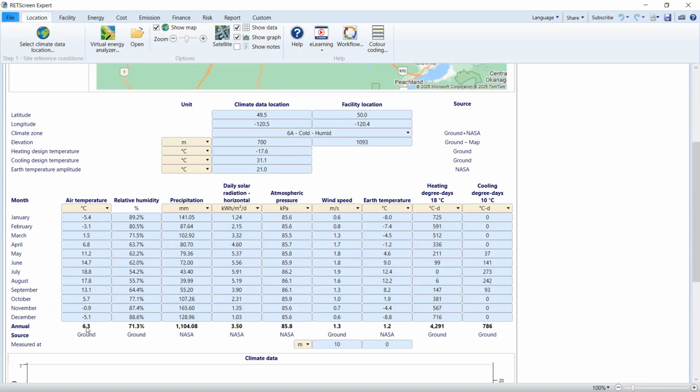And this site is a little bit colder than the standard test conditions of 15 degrees Celsius, which are used with a turbine to estimate the power output of a turbine. So the air is going to be more dense than in that test, and that'll tend to increase its output. This atmospheric pressure is lower than the atmospheric pressure at sea level, which is the assumption used when you're evaluating standard test conditions for a turbine. Why? Because we are at 1,093 meters above sea level, according to this.